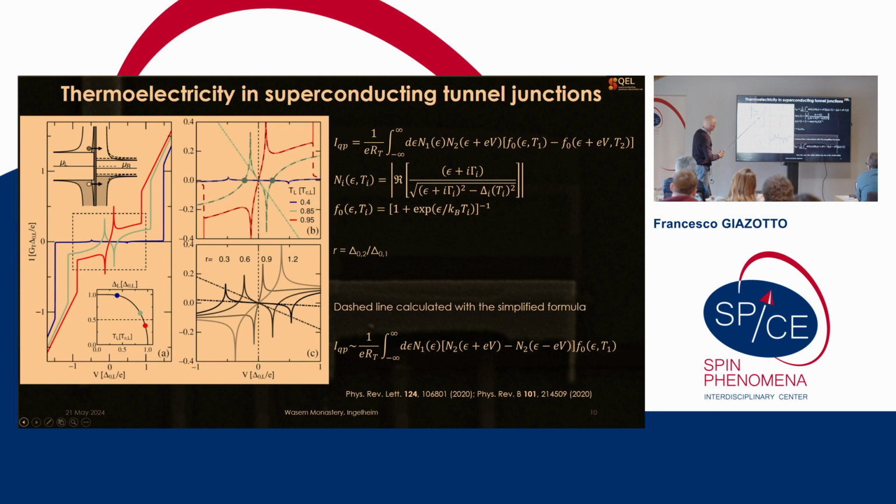The more interesting one here is probably this cyan one, at a larger temperature in the system. You see that it develops a completely negative peak. The curve maintains its antisymmetry, of course, but in the second and fourth quadrants of the IV characteristic, we have a finite response.